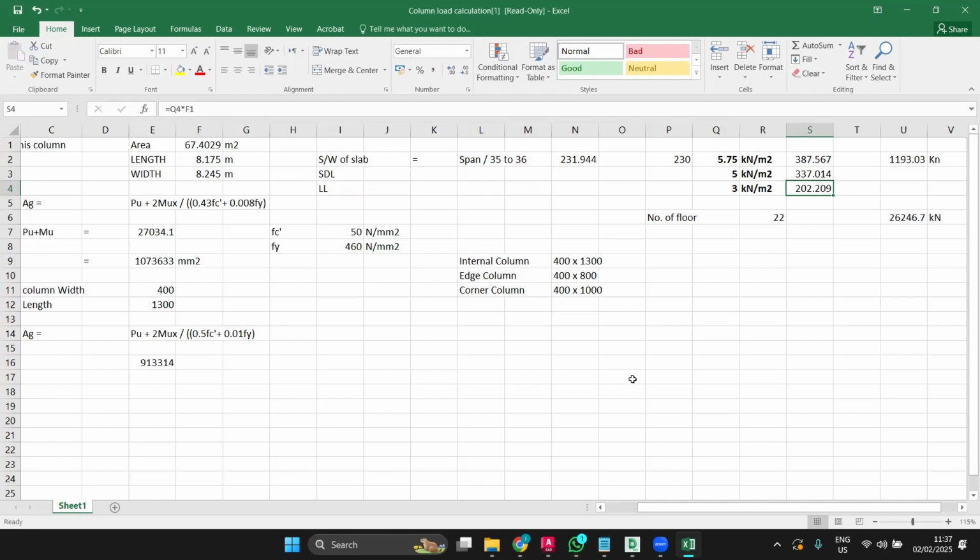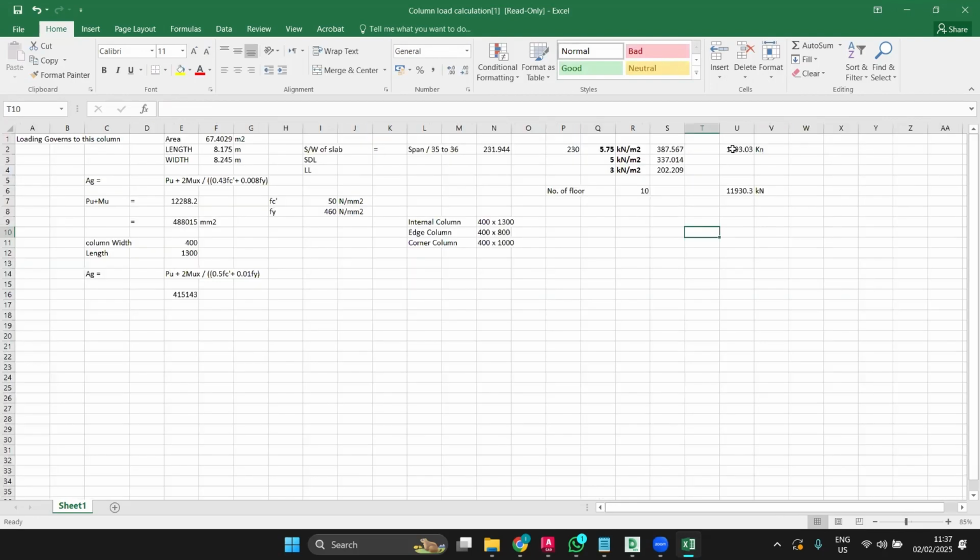How come you can only take typical floors here? 10 floors. Yeah, automatically the load has been changed. Very good actually. Click on it above. Minimize it. Yeah, click. Yeah, 1.2 times of dead load, 1.6 times of live load. Fantastic actually. Okay.